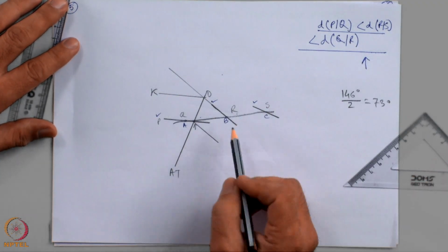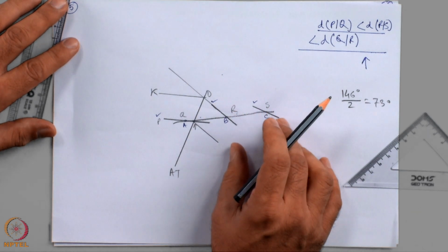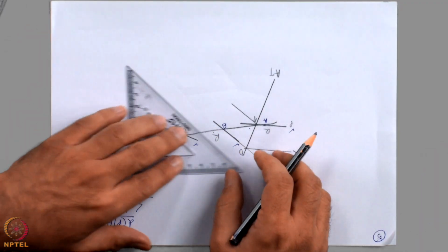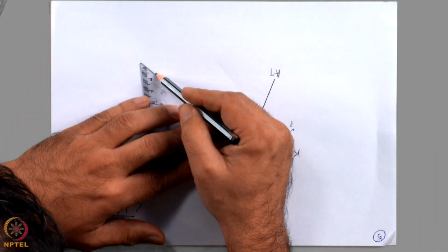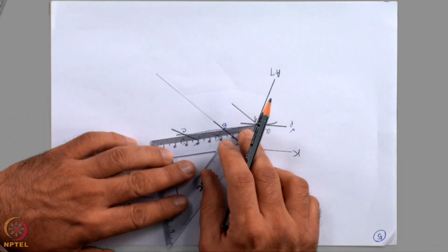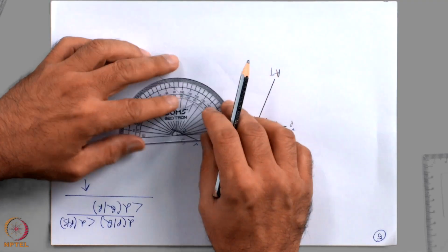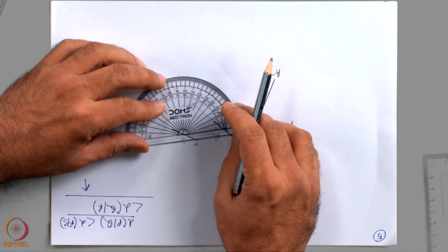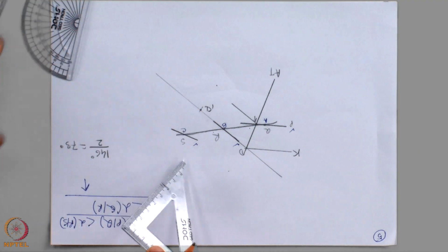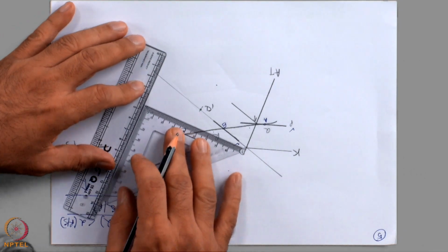Now, I am going to see the contact between Q and R and the contact between R and S and want to execute the work. To do that, I will flip the paper. Now, same process here, I will extend this up or basically down, since I have flipped the paper, join the BC points, find out this angle which is here 48 degrees. So, from point C I have to draw 48 degrees angle. By doing that, I have reached the point D dash. Now, from point D dash I have to draw a line parallel to this lithological contact.